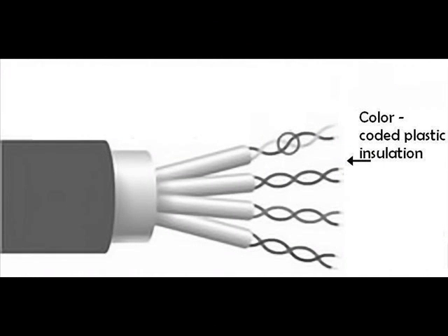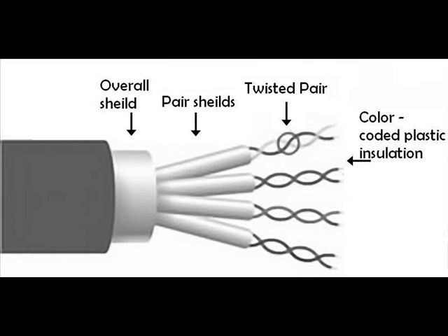The STP specs are copper wiring, covered in plastic insulation, put into the twisted pairs, given individual pair shields of metallic foil, and also covered by an overall shield of metallic braid or foil to avoid any interference and protected by plastic outer jacket from damage. Maximum length up to 100 meters. Transfer rate is only 10 to 100 megabits per second.